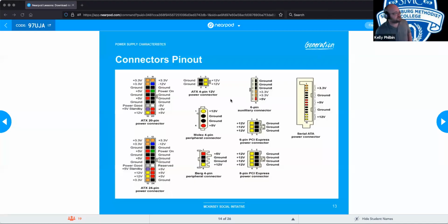There we go. All right, so here's a basic idea of a schematic. You should be able to eventually, not necessarily for the CompTIA, but for life, look at these and read that schematic as to what it is. You can see based on the coloring of the wires, like the orange is the +3, blue is -12, blacks are the grounds, whites are -5, red is +5, and yellow is +12. And then they also have a couple others like the +5 volt standby,